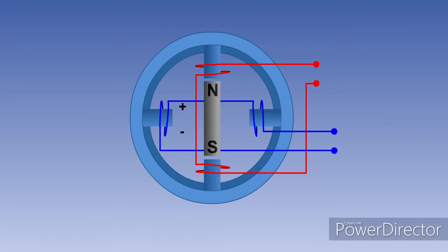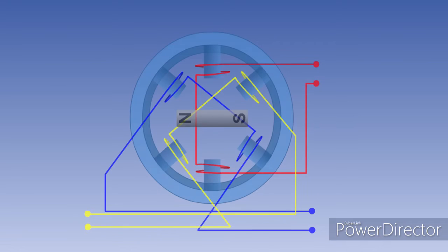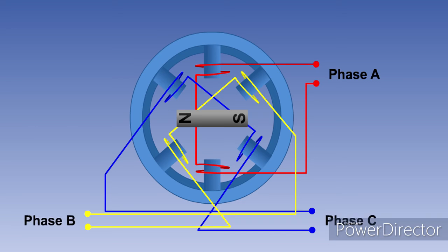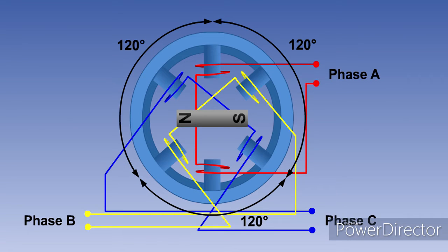Polyphase or multi-phase AC generators have two or more sets of single-phase armature windings, commonly known as phases, symmetrically spaced around the stator. The most common polyphase AC generator has three sets of armature windings. It is known as a three-phase generator and has become the standard AC generation system for aircraft. The phase windings are named A, B, and C. They are mechanically arranged to be at 120 degrees to each other, in the sequence A, B, C.